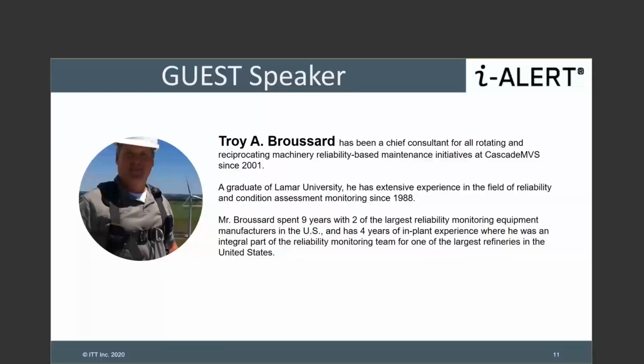Well, what occurs in many cases, either operations drives the pump into cavitation over days and weeks that you don't really see if you're doing route data collection all the time, or you start having an early stage bearing failure that the technician may not have his data collection set up to catch the early stages of that. The chatter starts happening, your seal starts to chatter and starts the failure part. So anytime you pull that pump out, they're going to put new bearings in anyway. So the bearings may be at a very early stage of fault, which has driven your seal to start chattering and fail. But they want to point to the seal being the failure point and not the bearings.